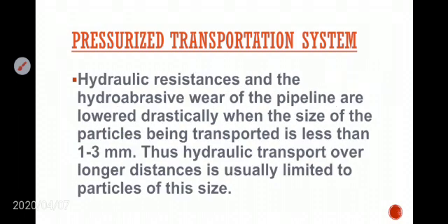Hydraulic resistances and the hydroabrasive wear of the pipeline are lowered drastically. That means the lower portion of the pipe will be eroded completely or slightly, because if the transporting mineral piece size is more, then obviously the lower portion of the pipeline will be eroded. That means the thickness will be decreased by continuous usage of this transportation system.